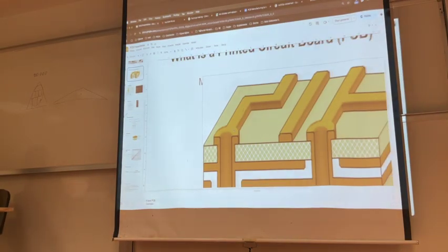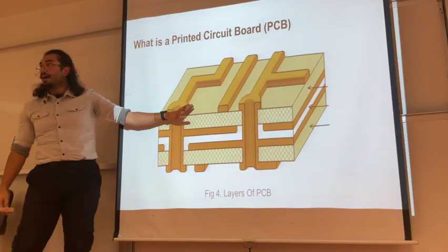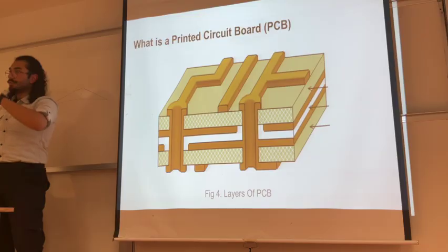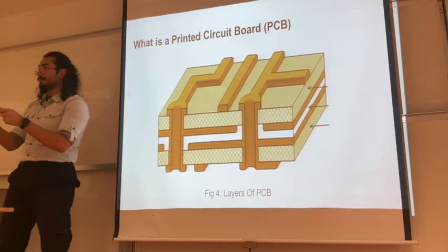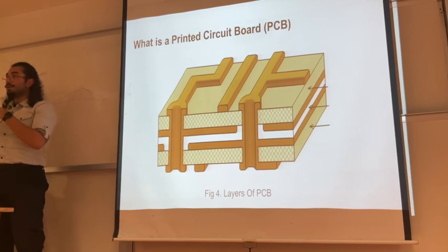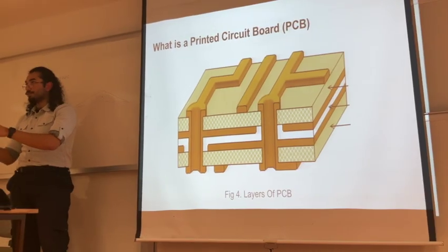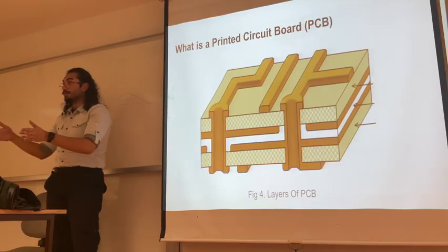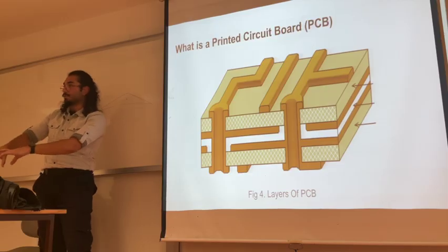On top of the PCB, I have a solder mask layer. And under that is the copper layer, copper film, and the visible part are pads. The copper visible parts are pads. So when you are going to solder a component, you want to know the exact measures, the height of it, the length of it. That's the footprint. The pads are the parts that we solder to.